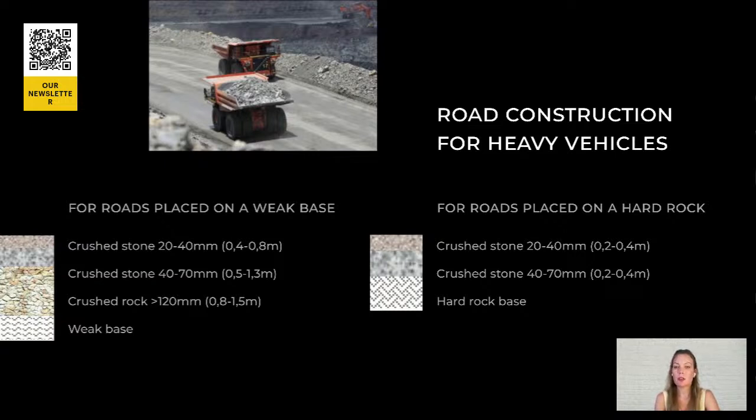Special attention should be given to the top layer, which directly contacts the tires. This layer must meet regulatory standards for parameters like flakiness, angularity, and wear resistance. For the best results, the top and final layer can be made from finely dispersed granite screenings cemented with a special liquid solution. This mixture fills all the voids and straightens the road surface. Maintaining these roads in good condition is also essential, using specialized equipment like graders, bulldozers, and loaders.